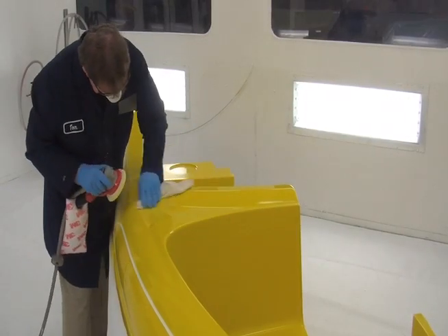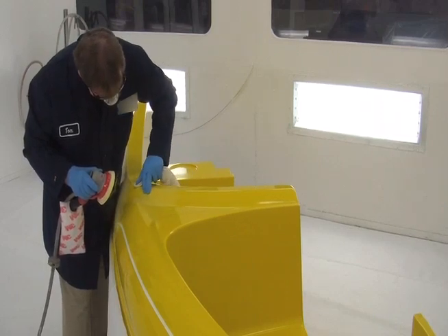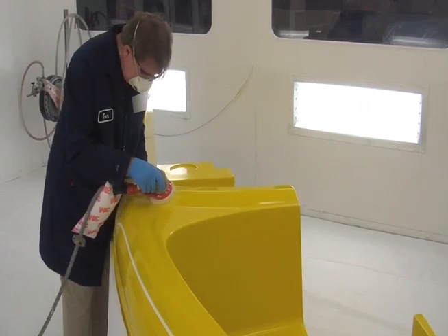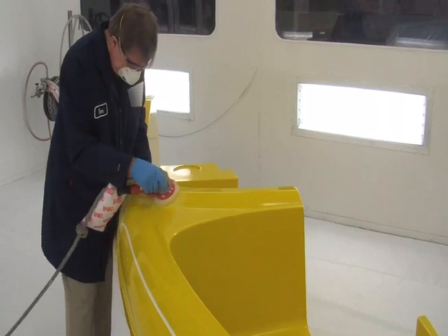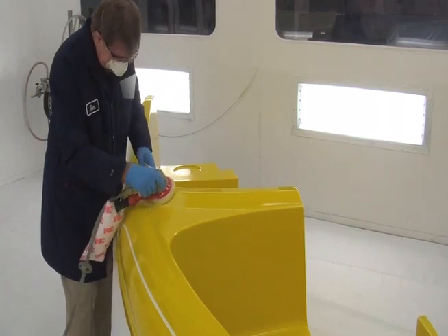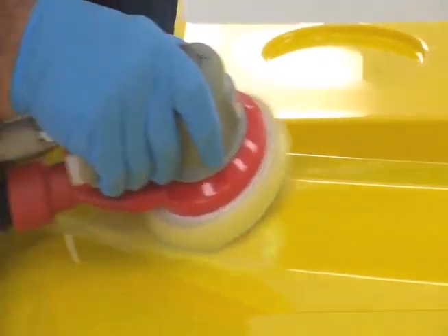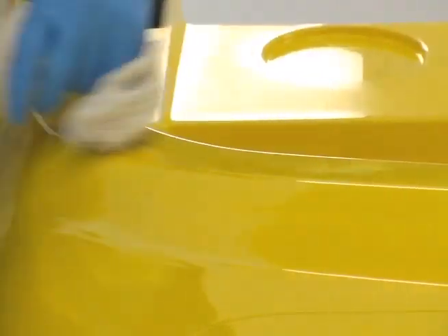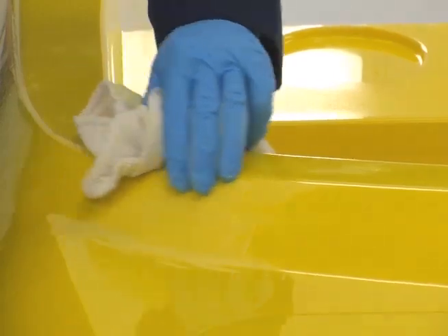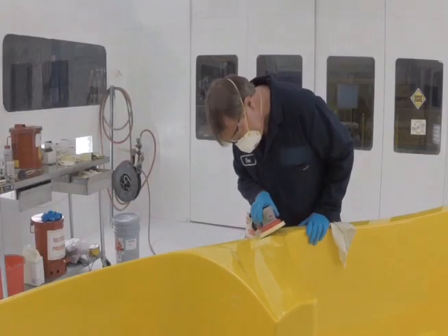When sanding larger areas, sand one direction for each grit size, for example, sand north-south with 400 grit and then east-west with 600 grit sandpaper. Always use a clean cloth to remove sanding dust, oils, wax and other contaminants, especially when changing to a different sandpaper grit.